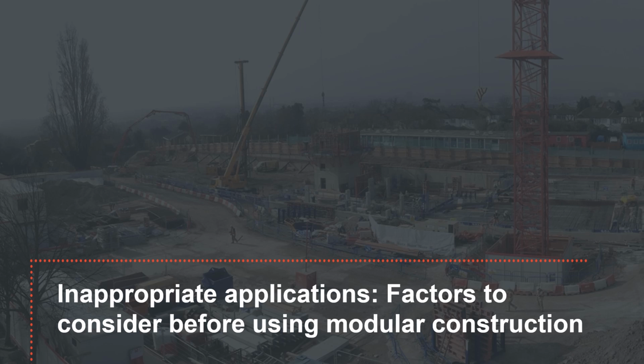However, if access to site is restricted due to poor quality roads, geographical location or space, noise and traffic limitations generally associated with city centre development, modular construction can be the perfect fit. Forward planning. Modular construction requires greater planning and investment up front, and ideally a design that incorporates repetition and modules. If this is not possible, then modular construction should be avoided.